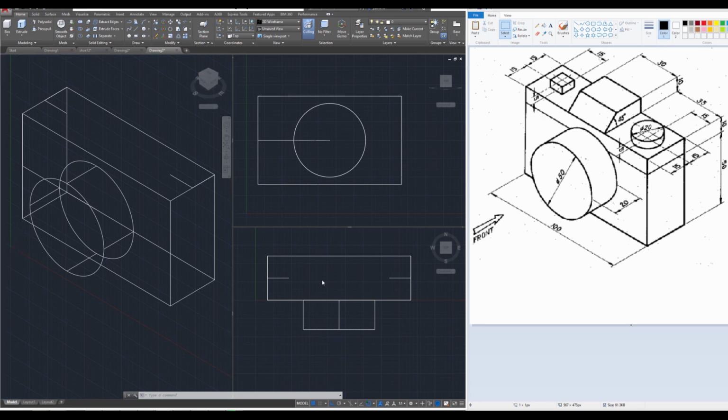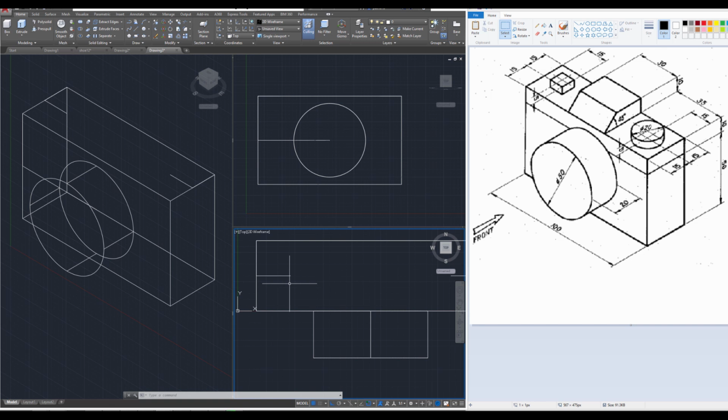In this view over here, I'm going to use the rectangle command again, REC, enter. And I'm going to start from this point. I'm going to draw out a 10, tab, 10, enter, rectangle. So you'll see that it positioned it, but it didn't quite position it correctly. That's fine. Use the move command, enter, and you're just going to select the rectangle, enter, and then hovering over it to the side, you'll notice that that little triangle should be appearing. And then I could go to the center, click on it, and move it over to here. So now it's centered correctly.